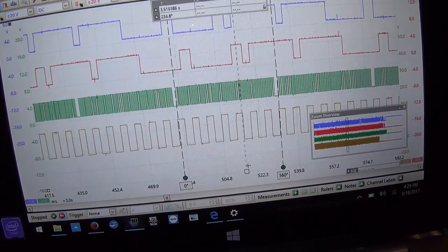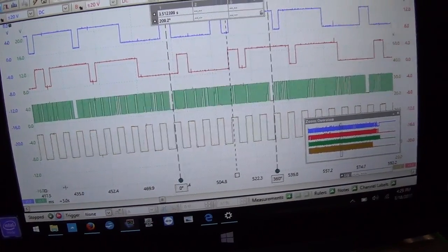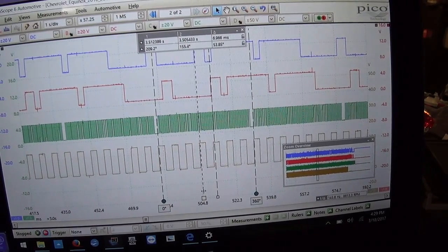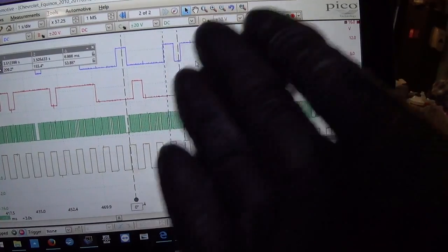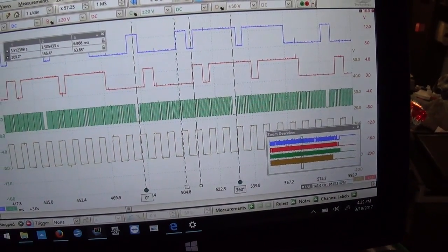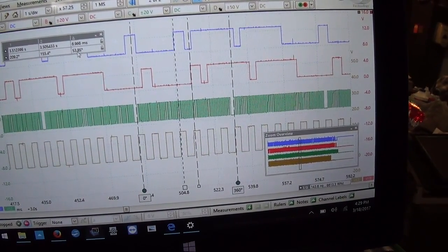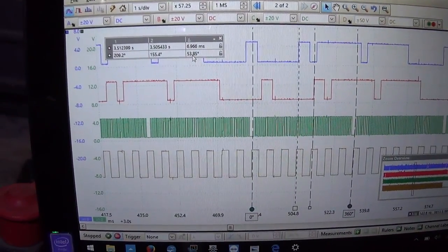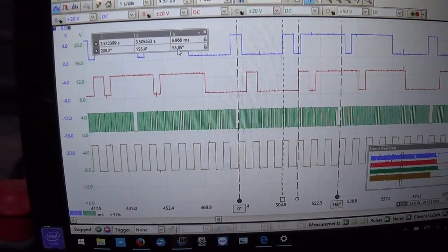So now we can say, okay, that step should potentially line up with that step right there. You would think maybe they should line up at idle. And the difference between our two cursors right there is 53 degrees of crankshaft rotation. That might be good, that might be bad, but we'll write that number down, and if anything changes, we'll be able to compare it to this waveform.